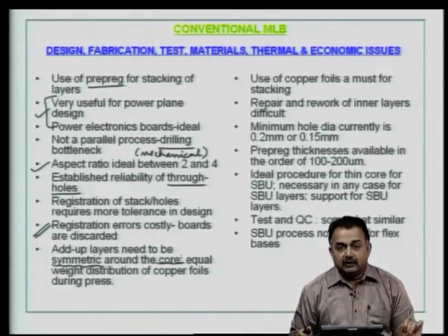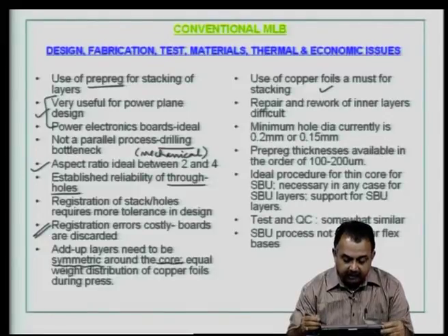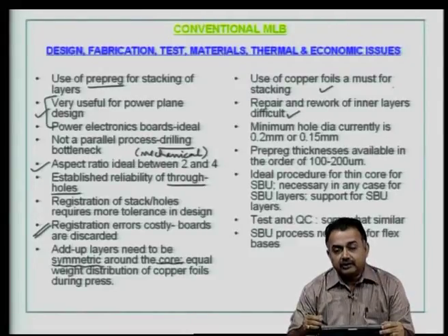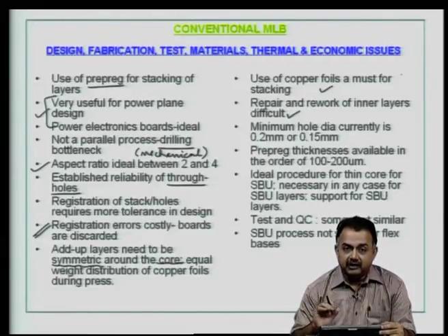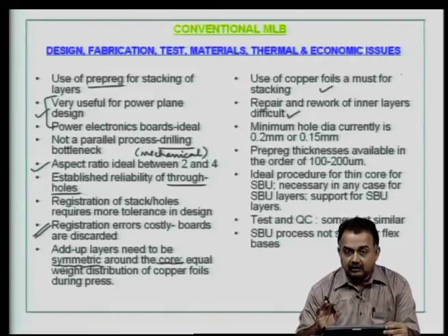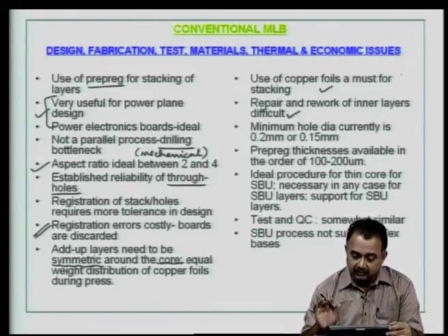Use of copper foils is a must for stacking. So, you will use a pre-preg as well as copper foils. Repair and rework of inner layers is difficult. So, we have seen at least a couple of methods to fabricate conventional multilayer boards, and the inner layers have to be immediately quality checked for electrical shorts and opens as well as any process defects on the surface.